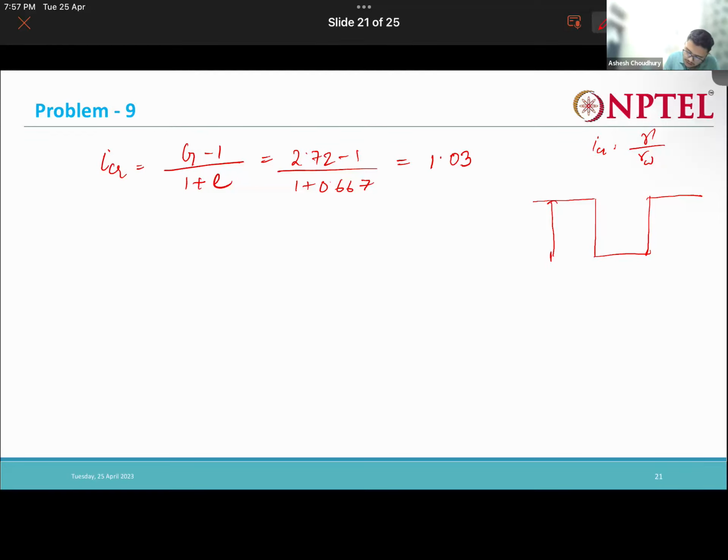These things are actually used in the field regularly. Some geosynthetic materials are provided. When we do the filling, say you're building something, first of all, say this is the subgrade. You put some geosynthetic material here, and outside drains are there.